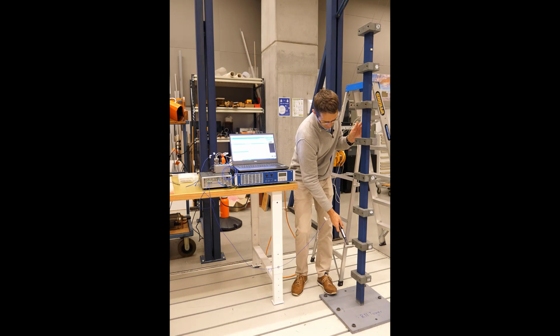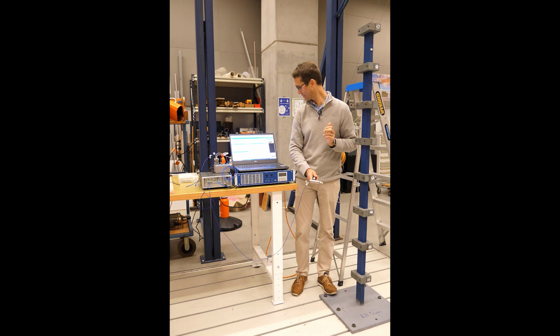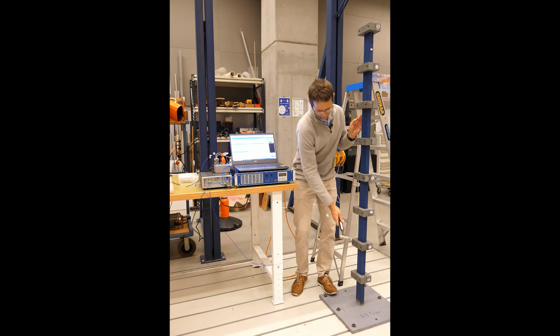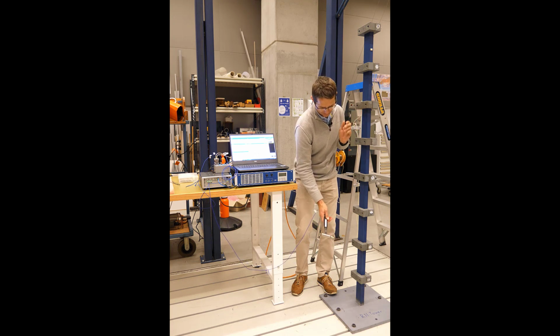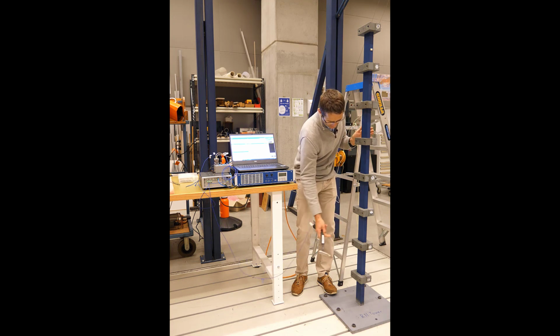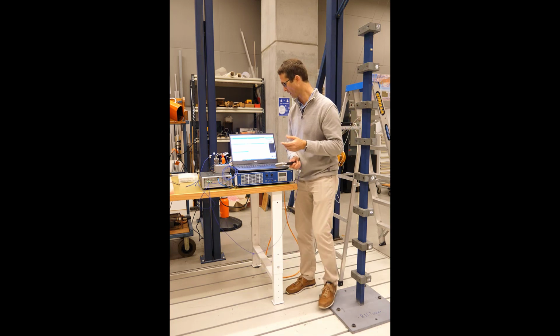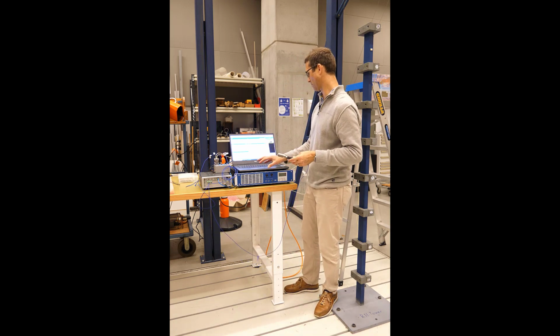Now moving up to level 2. And it's important when I'm striking that I'm tapping the tower gently and I'm getting a clean, sharp impact. I'm tapping the tower in the X direction and at the same location on that degree of freedom. If there's any movement or change in direction, then obviously I get a different FRF each time. My averaging won't be particularly good.